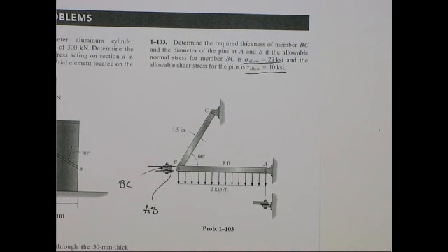Now here there is no factor of safety, so here they're calling it allowable. So that's basically what we got before. That would be, if they're designing to yield, the yield over the factor of safety, or if it's brittle and they're designing to actual failure or some other fatigue type of loading, it's that value divided by the factor of safety. But they've already done that for you, so what we're going to consider is those values are the ones that we're going to design to, all right?